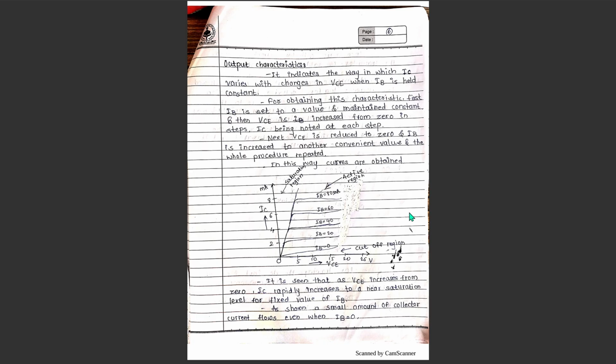When output voltage VCE is at 0 volts, the emitter base junction is forward biased by input voltage VBE. The emitter base junction acts like a normal PN junction diode. So the input characteristics of the CE configuration is the same as the characteristics of a normal PN junction diode. In CE configuration, the input current IB is produced in the base region, which is lightly doped and has small width. So the base region produces only a small input current IB.